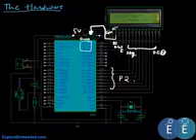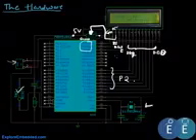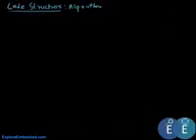Now apart from this, for the LCD to work, your controller should have other basic stuff. So you should have the crystal connected, you should have the reset, and you should power it up, which could be through a DC adapter or a battery. So these are the basic connections for an LCD to operate in 8-bit mode. As you could observe, the 8-bit mode has all the data lines DB0 to DB7 connected to a microcontroller port pin. Next we'll go ahead and discuss what could be the possible way to write the software for this.